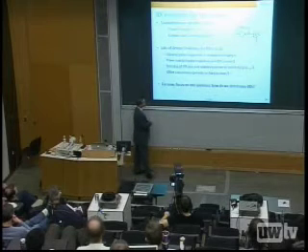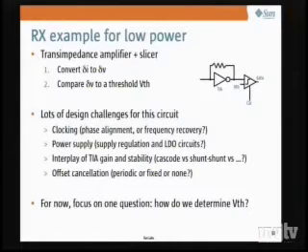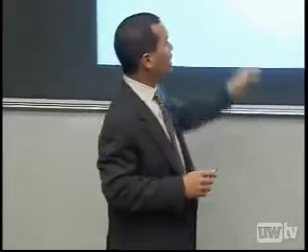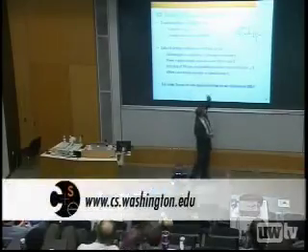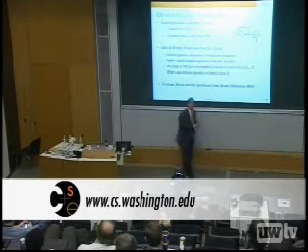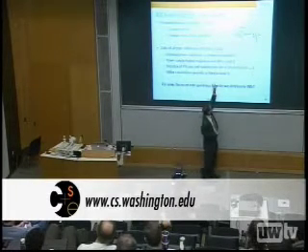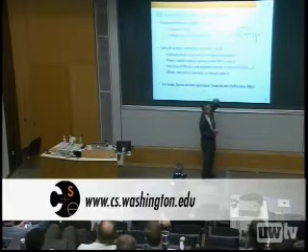As an example of some of the work we did in a circuit sense, we can think about some of the components of this photonics link. So let's look at the receiver, because the receiver is kind of interesting. I've got an input on the circuit here from the left. That's coming from a photodiode. It's spitting out a very small amount of current, about 20 microamps average, anywhere from 10 to 30 varying. And I've got to take that and change that current into a voltage at the outside. That's done by a TIA, a transimpedance amplifier, because it turns I into V, so transimpedance, and it's becoming bigger, so it's an amplifier. And I compare that small voltage with a reference to get my actual data.